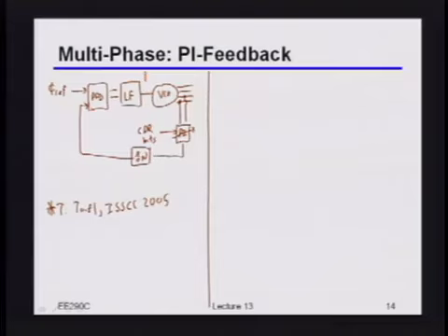Remember, I want a full 360 degrees of range, and I want to do that in a fairly transparent way, but you're absolutely right. I could just somehow muck with the phase frequency detector to adjust its offset. There's something else we can do that mucks with the phase frequency detector that's, again, kind of subtle, but go ahead. Can you put like 4 divide by n's and then do a PI? Yeah, there we go. Okay, so that's indeed pretty much exactly what you would do.